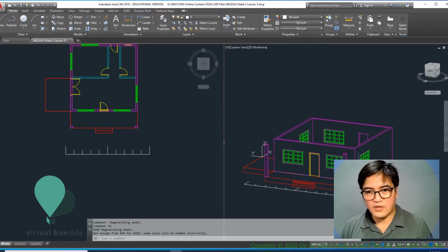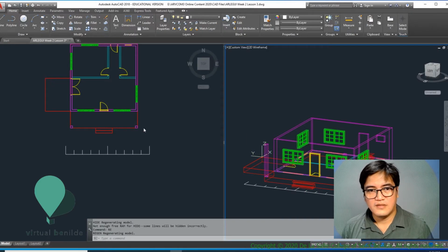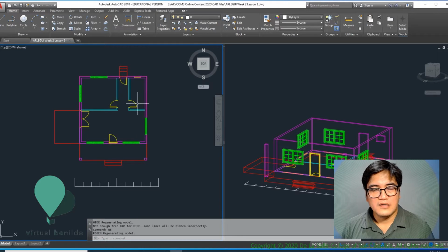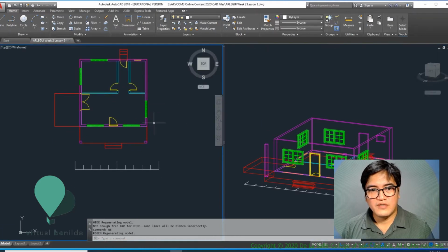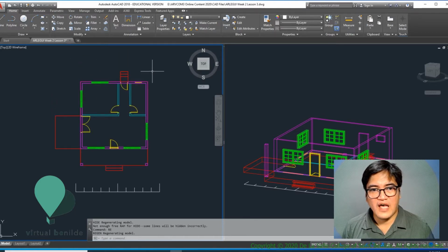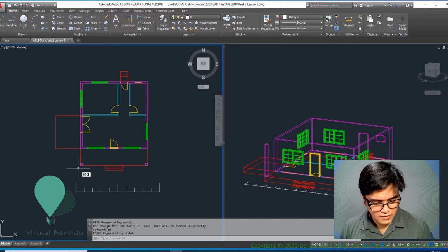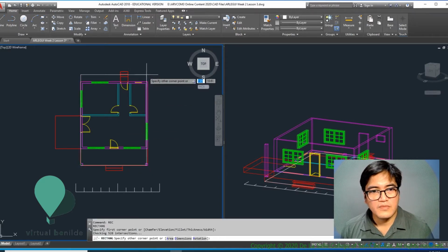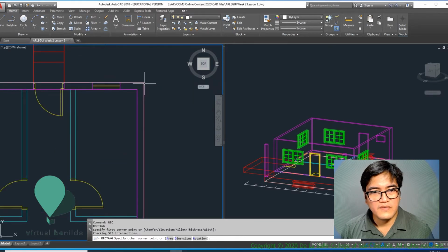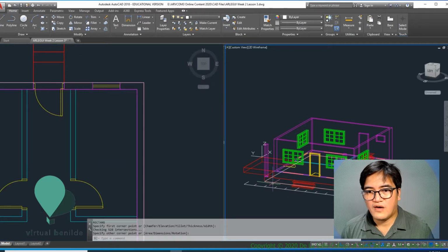So we're nearing completion. It's just a rooftop now. Now for the rooftop, I'm going to generate it from first a rectangle. So it's going to be overhanging here onto the porch, also over the porch here, roughly about 1.2 meters. I'm thinking about that. So I'm in layer 0 for the meantime. I'm going to be constructing a few things here. So REC. I'm going to reference that corner over to this corner because I need to offset this.